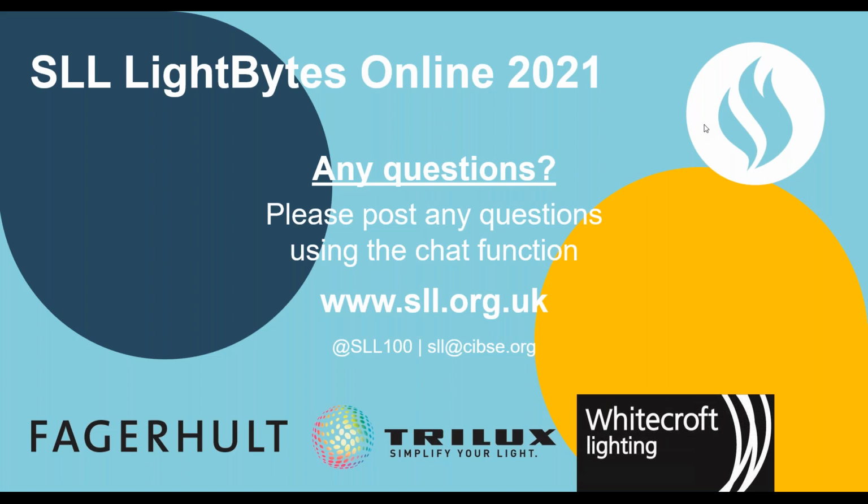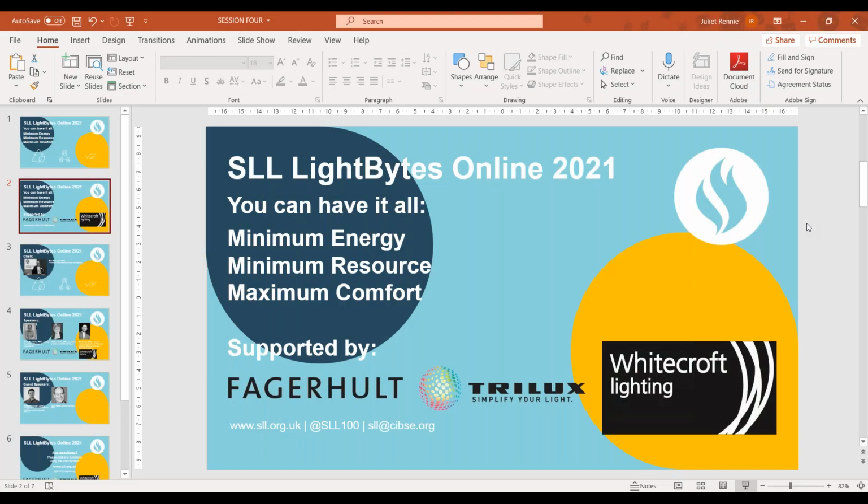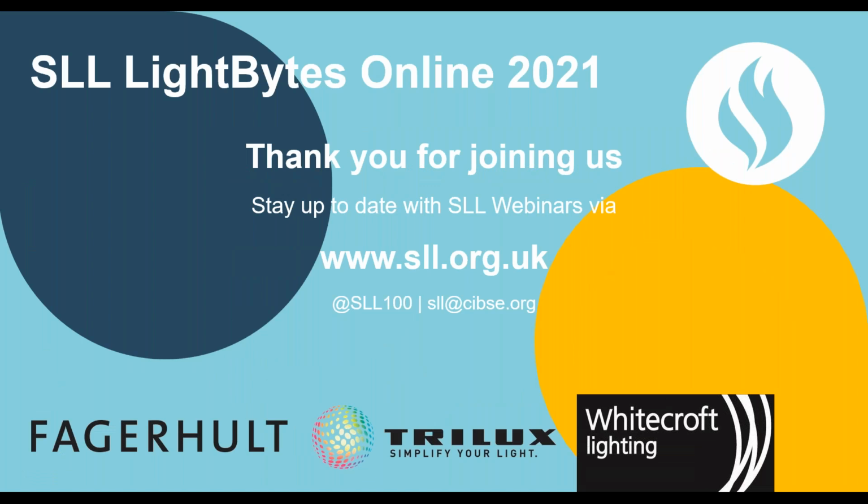Right, embedding usage data into luminaires that can be recovered at the end of use is poor value, says Michael. We need luminaires to tell us how many hours they are doing in real time and the level of output, and that can also be analyzed in real time to help users optimize energy use. I think that comes back to the comment I said before about supporting the relationship in the monitoring using controls, and getting greater analytics. I think I agree with that comment.